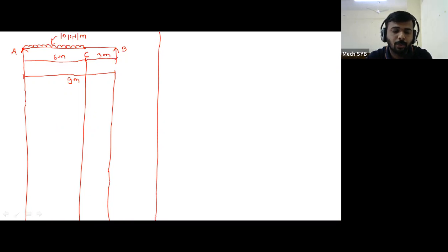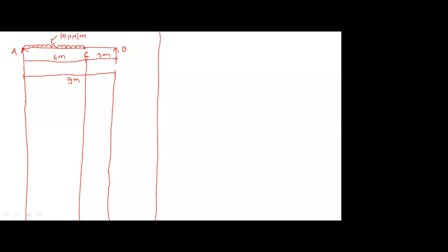So the beam is subjected to only one load, that is UDL. There is no point load, no UVL, no couple. But if the UDL is given, then what exactly do we have to do in the loading diagram? Because we have to make some change in the loading diagram and then go for the further calculation. So if the beam is subjected to the UDL or the UVL, what is our first requirement? We have discussed in the types of loads. What is our first requirement? Convert into point load. Correct.